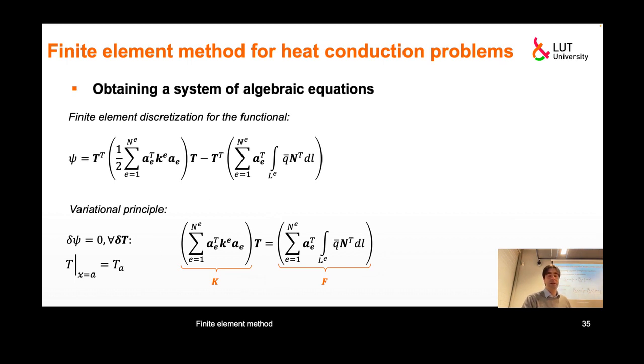And what is that? It's nothing but a system of linear equations with respect to unknown nodal temperature values. So this factor in front of this is a matrix, of course, because those are matrices and matrix products. And what's in parentheses here, we can call it K, the global conductivity matrix. And what's in the right hand side is a column of values. If you check, you will see that. We'll call it F. And then it's an equation of standard type, KT equals F.